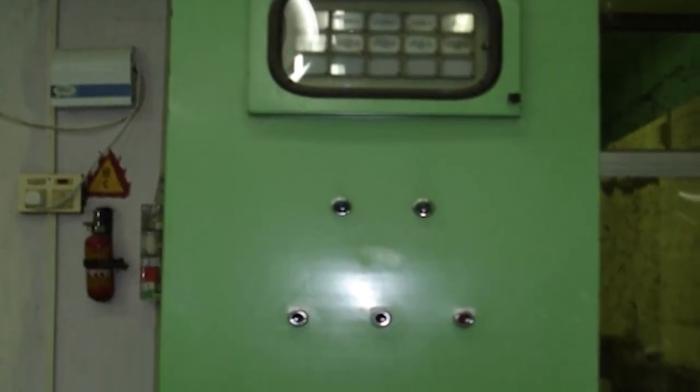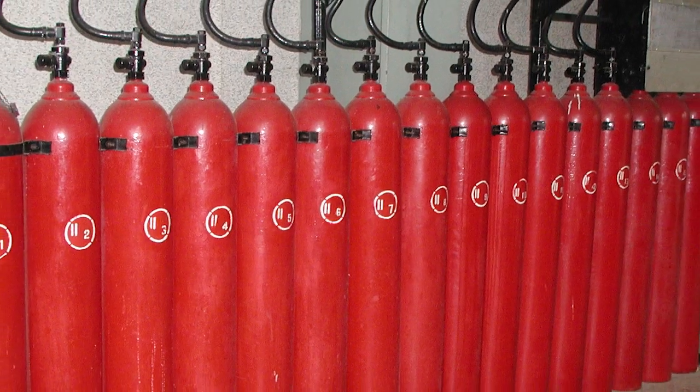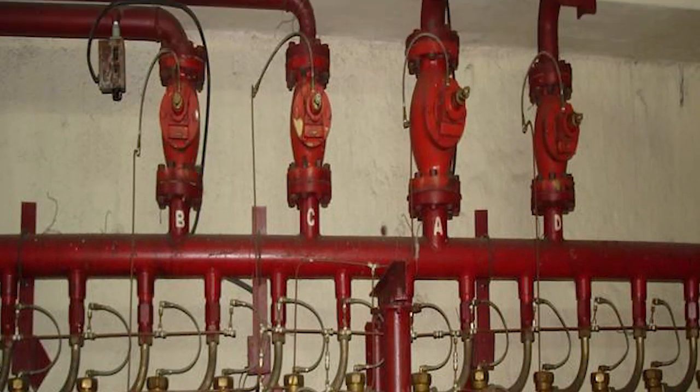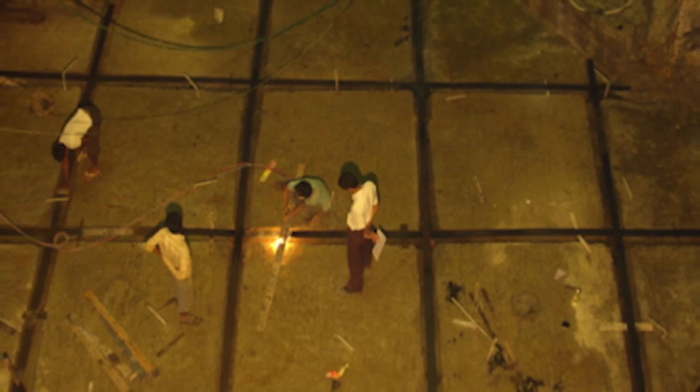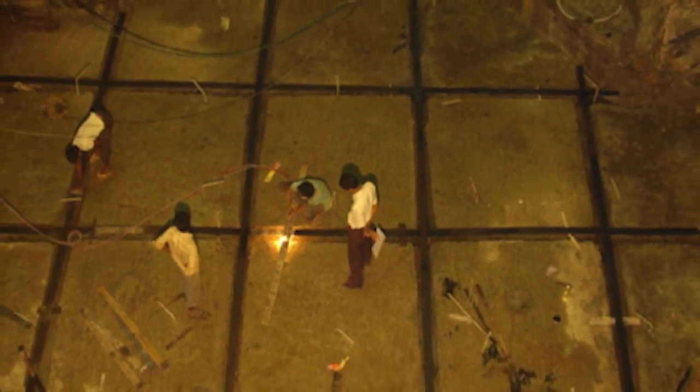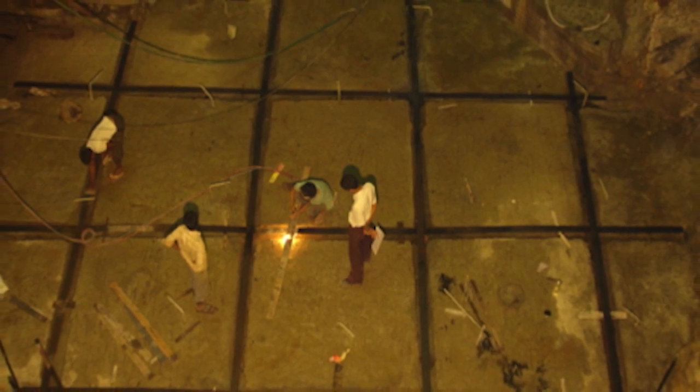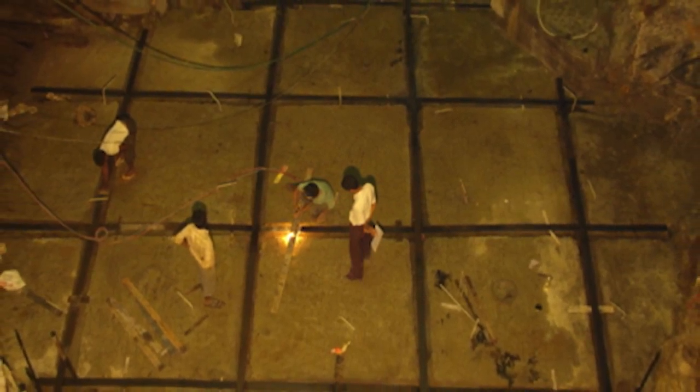Illumination system. It is the normal lighting system which includes indoor and outdoor lighting of complete powerhouse and adjoining areas. Firefighting system. It is the fire protection system to take care of accidental event of fire in the power plant. Grounding. This is the powerhouse electrical earthing system. Improper grounding system may lead to failure of equipment, inappropriate function of protection equipment, especially related to earth fault, and even human casualty in case of fault.